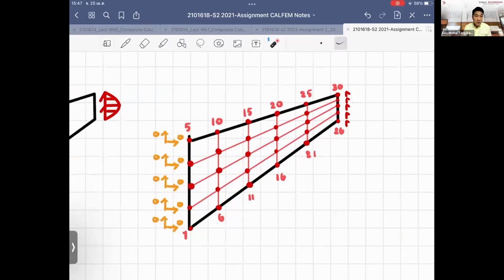I think you can trace the information of how we can make the input files from the EDOF. The DOF is the degrees of freedom, where we have restrained the support here, which is the cantilever beam. So we don't allow the translation along the nodes on the left-hand side line. We give them 0 degrees of freedom, and then we keep running the number of degrees of freedom.